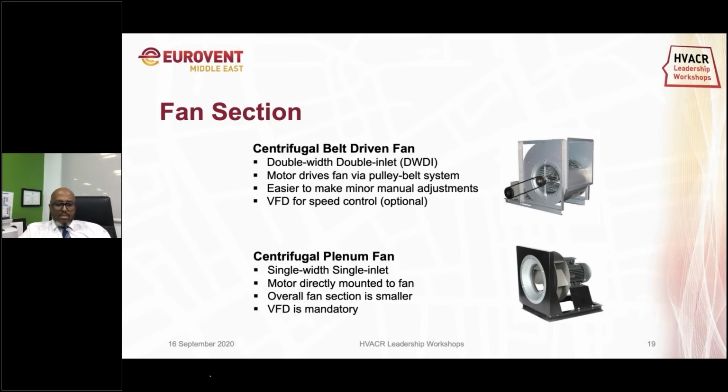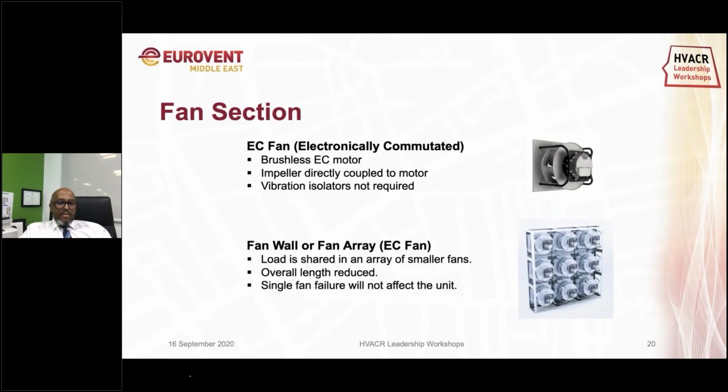Centrifugal plenum fan is also on the bottom, you can see single width, obviously with the motor direct mounted to the fan. Overall the fan section is smaller. VFD is mandatory, obviously, in certain criteria. Again, we see more of the EC fans. This is obviously becoming more popular with most customers and clients. It's brushless, the impeller direct coupled to the motor. Vibration isolators are not used, sorry. Fan wall or the fan array, we can see here from the other side as well.